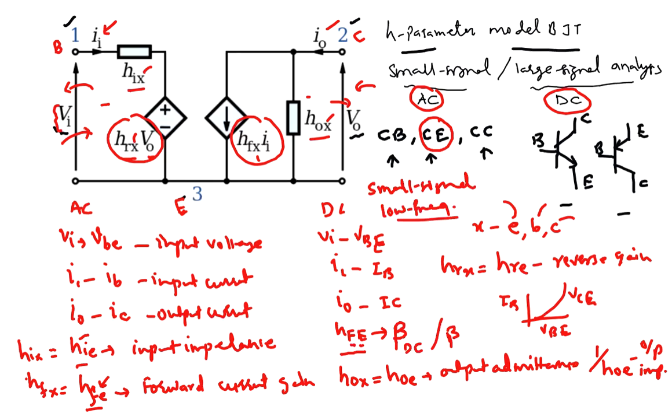When you want to operate circuits or devices incorporating a BJT for high frequency analysis, then the inter-electrode capacitances, which are important at high frequencies, must be added. So you will have to add the capacitances in the model, but we'll see that some other time. Okay, so that's all. So this is how you understand your parameters for it.